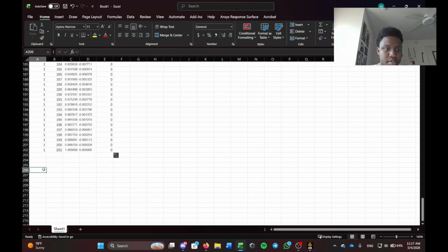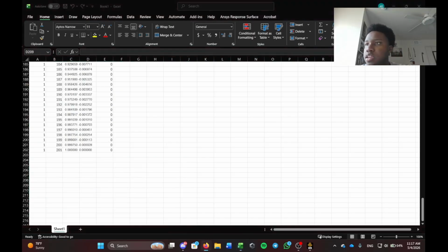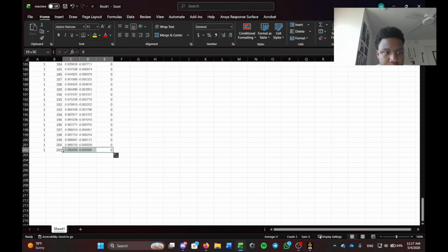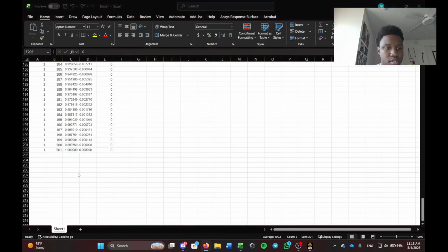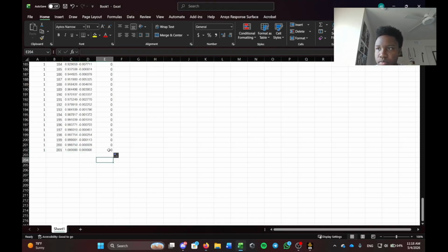And then if you import this as a CSV file doing the other method that I showed you, you'll have other stuff. Just delete that, as we do not need any of that. And then for this last point here, where it's attempting to close our airfoil, we are going to actually get rid of that right there. And then once you close that up, you just want to change this 1 to 0, like so.